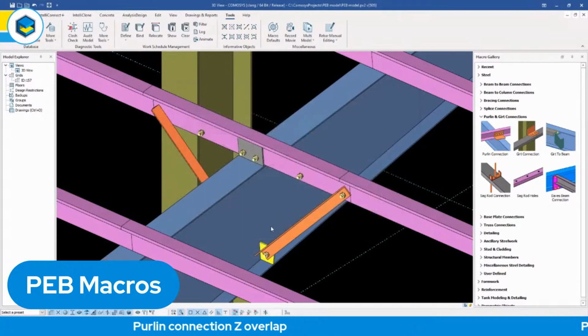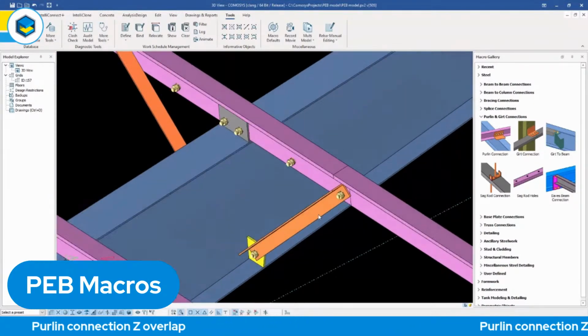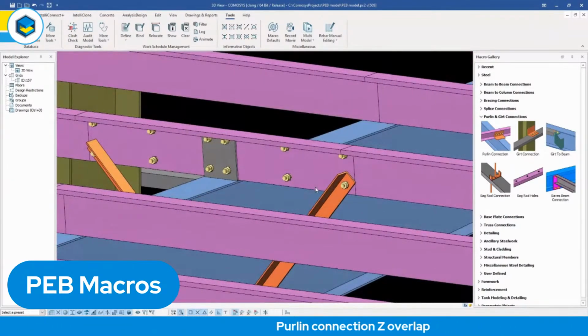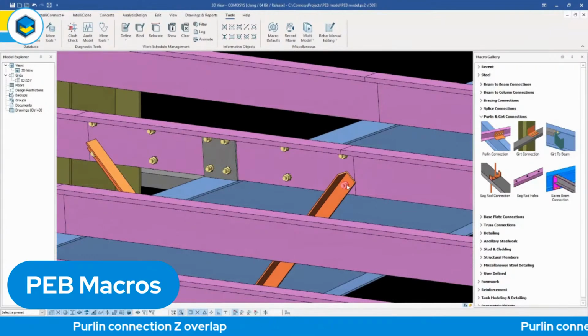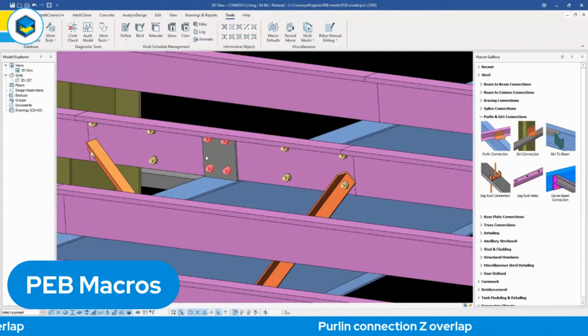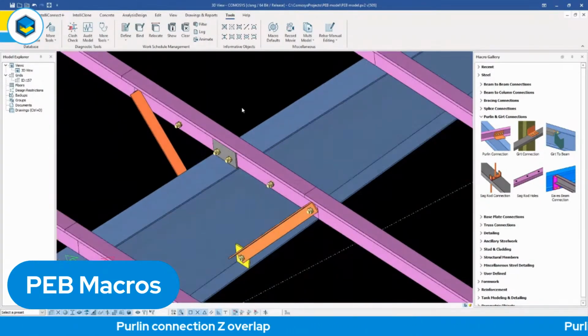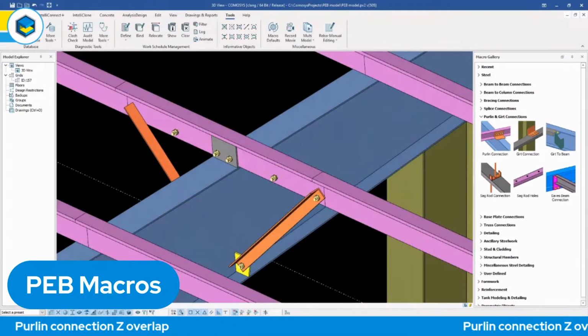And if I do that, immediately those struts are created on either side of the connection. Now, since the bolt IDs are different, this is a single bolt because it's going through the strut as well, and this is a separate bolt. These two are one ID, and these four are one ID because they're going through the plate as well as the other one. So this is a very handy way of creating this new Z-type Purlin overlapped Purlin connection,